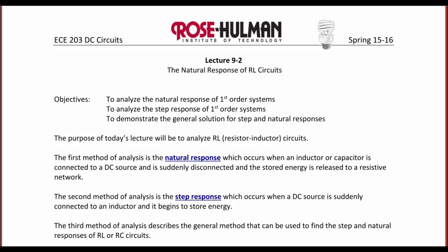In today's lecture we will focus on RL circuits, which include a resistor and an inductor. These are first-order circuits because they can be described by a first-order differential equation. The natural response of a circuit occurs when an inductor or capacitor is connected to a DC source and is suddenly disconnected, and the stored energy is released into a resistive network.